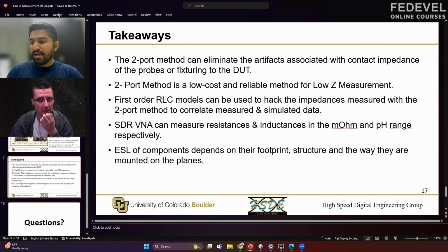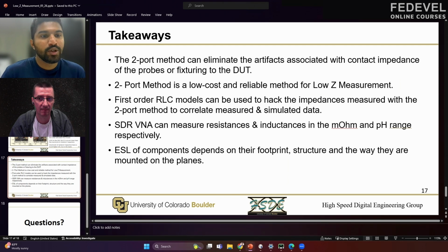The probes that I have used come with the VNA. But you only use cables and you need special connectors for your test setup. Oh, if you would like to measure a real board, you mean the UFL connectors, connecting to pigtails. Yes, a good idea to measure your board, the PCB, is to have UFL connectors on your PCB and then connect them through pigtails to the VNA cables.